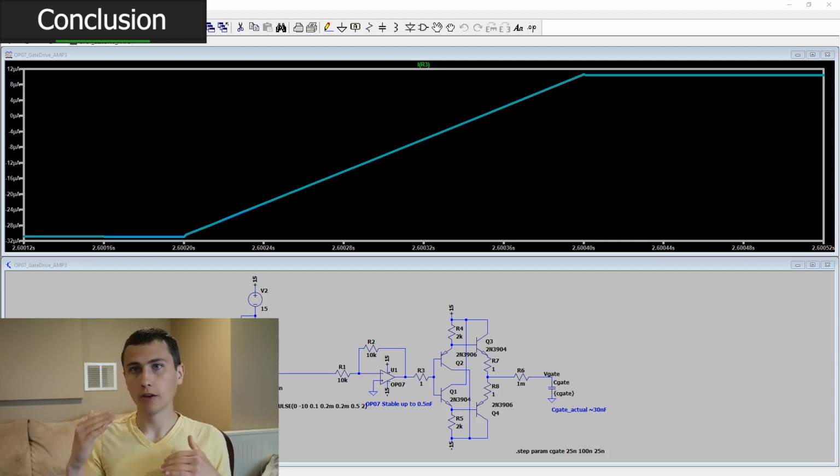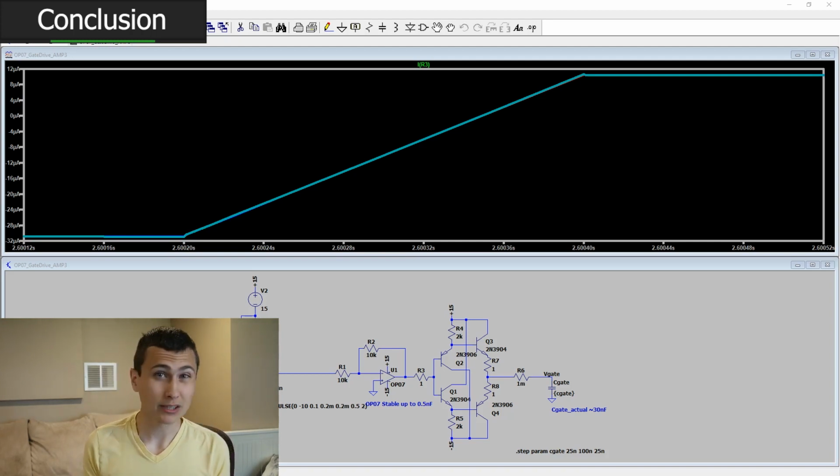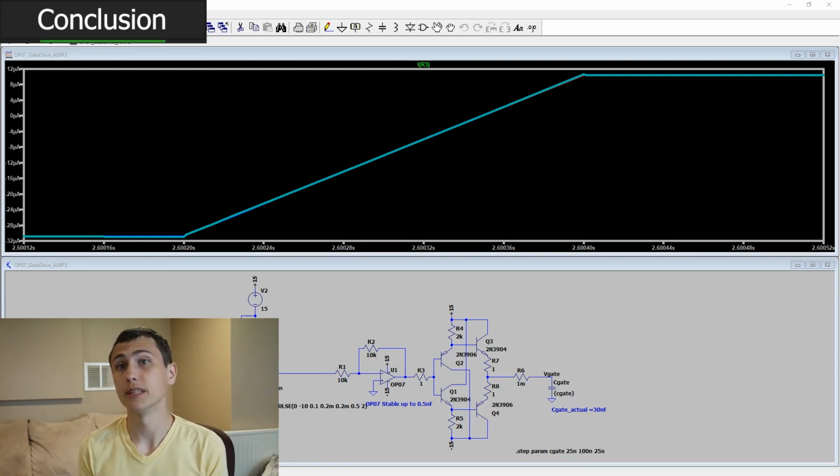So when you boot, there might be a small moment where the FET behaves slightly different than you would expect. Maybe it's 10 millivolts, maybe it's 100, maybe it's a volt. But we've got plus or minus 15 volts to play with. There's plenty of room here to compensate for that error. And if worst comes to worst, we can just add a series resistor, maybe 100 ohms, 50 ohms, tie it straight to the gate from the output of our OpAmp, and just accept that the transient response will not be sufficient.